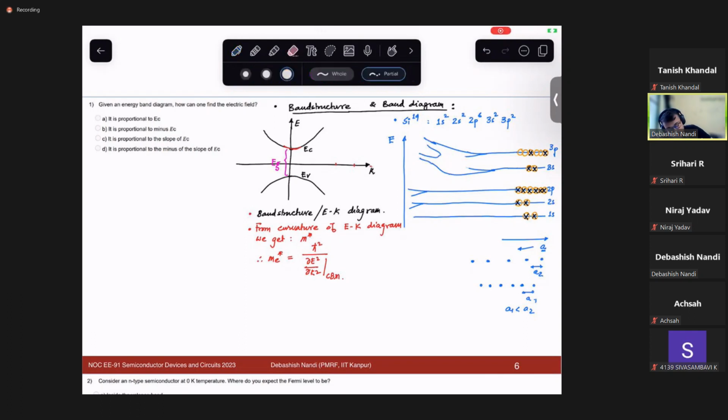What happens in the semiconductor case is that your atomic distance falls around this region. Your A for a semiconductor falls around this region. So you have a total of 8 states. 6 available, 2 filled here, and 2 available, 2 filled there.